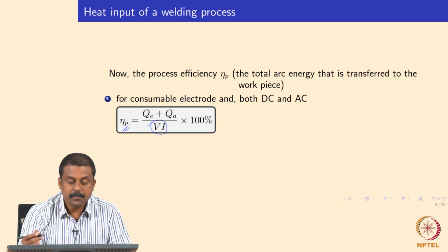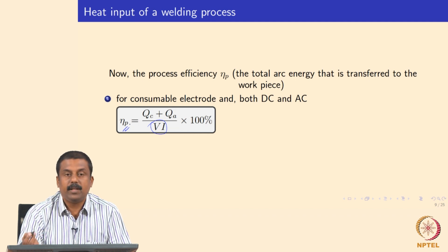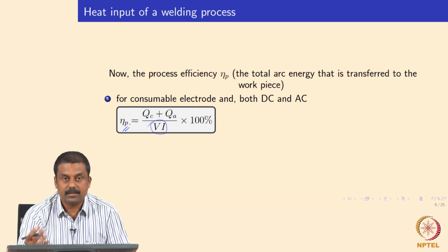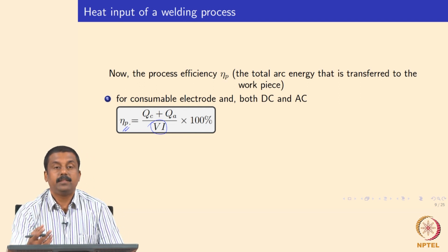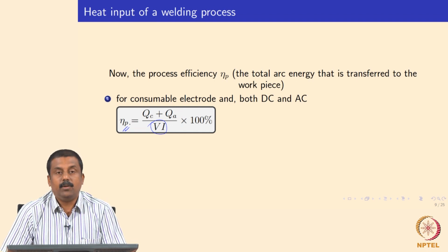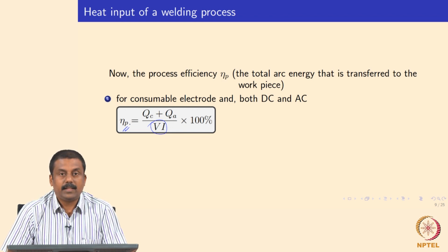So in the conventional GMAW process, the energy efficiency is not that significant, but it is much more than in the laser welding process, because for laser welding we already looked at the absorption of the laser by the workpiece, which is extremely small. Whereas in this case, the heat transfer from the arc is entirely determined by the atmosphere as well as the polarity.